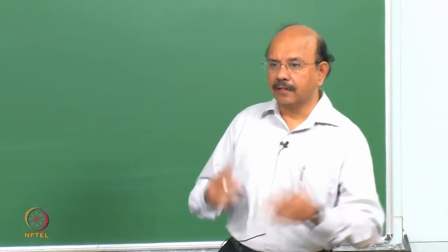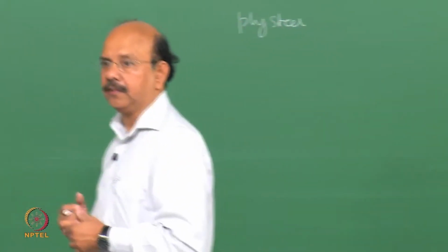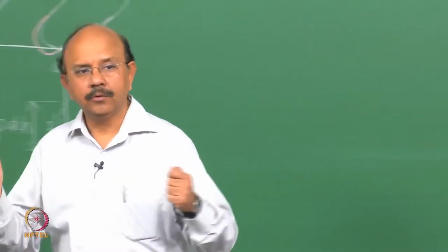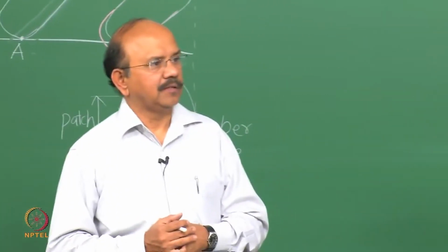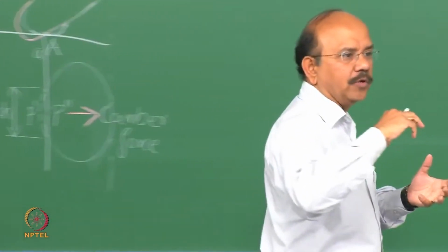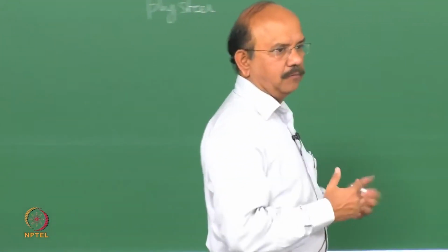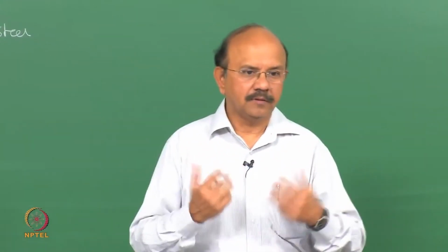It runs at an angle, and we said that in composite laminate ply theory, when you stretch this kind of composite material, there's a coupling that happens, so that when I stretch it, there is going to be a moment. In other words, force and moment have a coupling term.